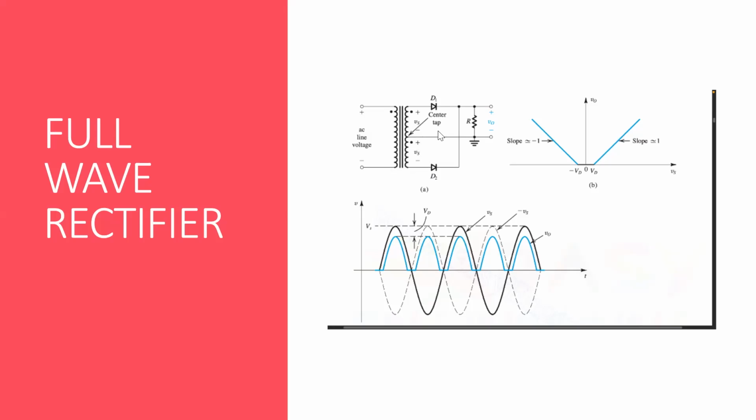And this is a way through which we can see it is two half-wave rectifiers in opposite directions, which is a nice way to make the full wave rectifier. And we can see here the same curve, and the gap is again due to the VD voltage drop in the diode, and this is V naught versus Vs. So it is directly proportional because V naught is IR.